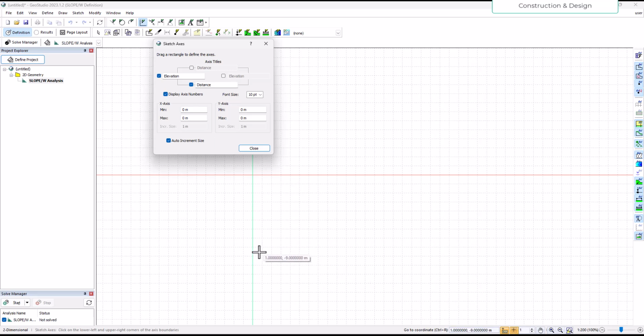The basic idea is for elevation, for one particular borehole, elevation will be like this, and then from one borehole, there's a certain distance, and at that distance there will be another borehole, and then the elevation data will be plotted like this, and then all of these will form a layer throughout. We'll just extrapolate it to form a layer.